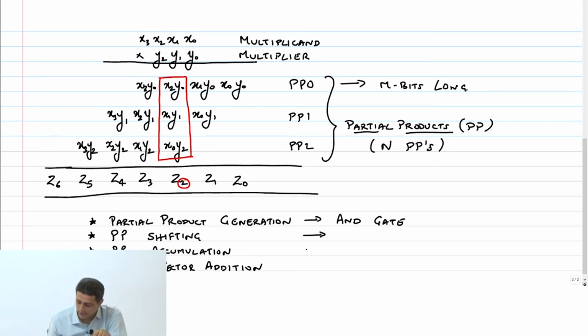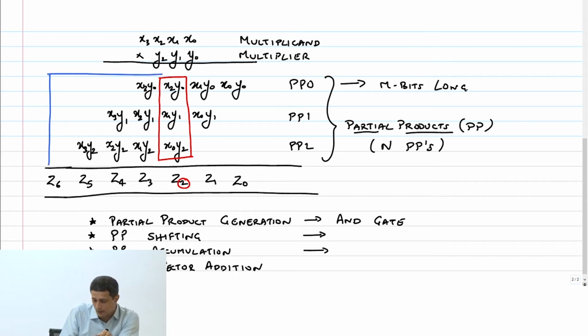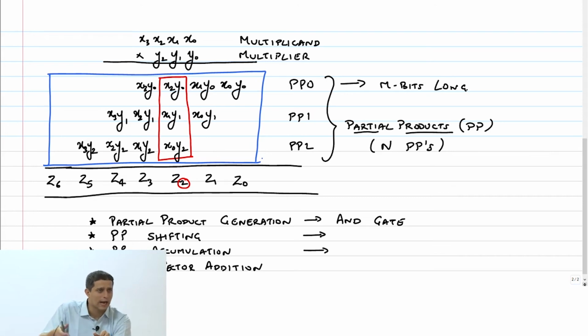Okay, so let's come to the next thing. What do you need in order to do partial product accumulation? You need an array of full adders. We have to arrange this so that we can perform this operation here, right? You clearly see there is an array of terms that need to be added in a particular way, and you need to provide as many full adders as needed to perform these many additions there, right? So this is nothing but an array of full adders.